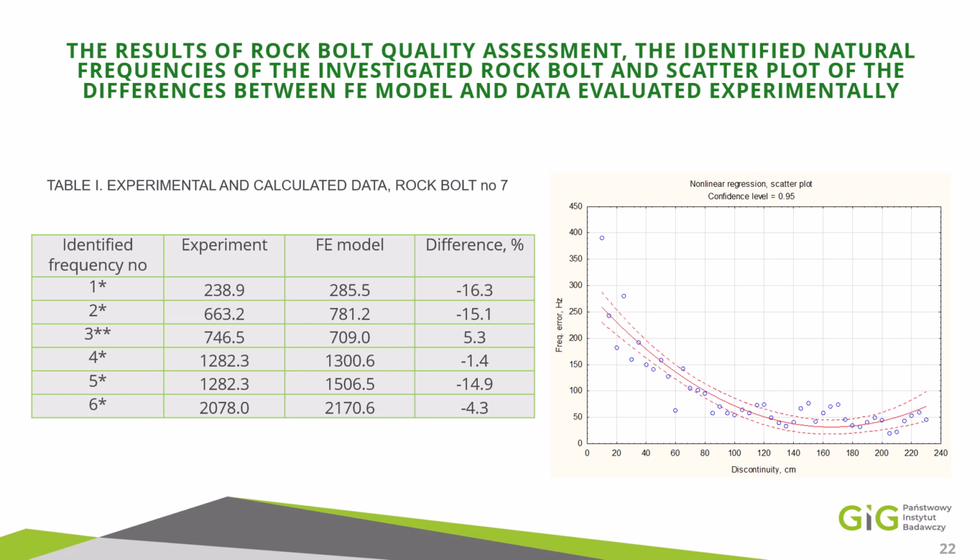The rock bolt is inserted up to half its length. Then is the turning phase, with continuous insertion of the rock bolt up to the end of the hole, and depending on the environmental conditions, the time is about 10 seconds. There's a spinning phase, about 4 or 5 seconds, and the hold phase about 15 seconds.